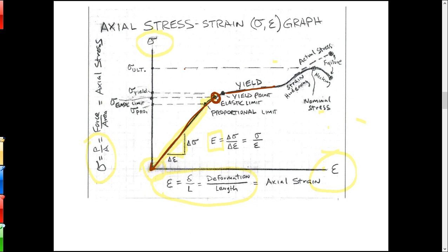Yeah, question, Josh? But if you're like strain hardening a material, then you would want to carefully adjust to that right point, and then come back and go out and come back. Yeah, right. Yeah, I was about to say that. Like cylinder head bolts, you have to stretch it. Yeah, there is something called strain hardening where you actually go beyond that limit, then release. Yeah, and you create a new material, basically new material properties.